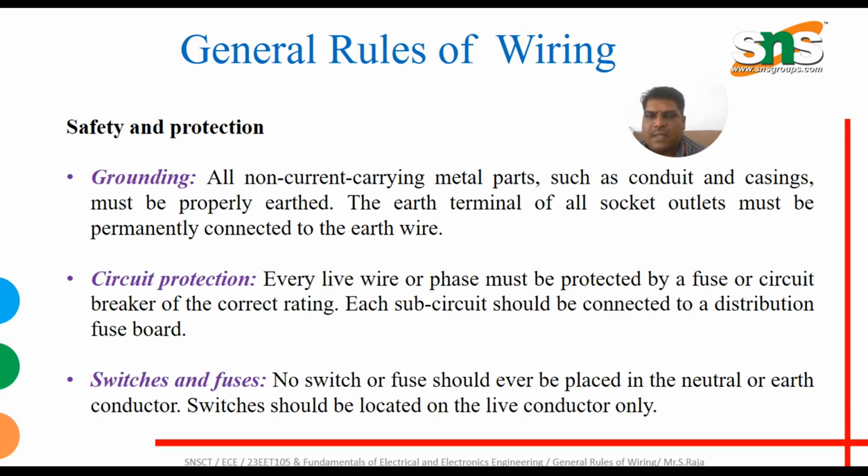Switches and fuses. No switch or fuse should ever be placed in a neutral or earth conductor. Switches should be located on the live conductor only. If you see in your classroom, the switches are above the ground level, and we have to place proper grounding and proper circuit protection for all the safety precautions.